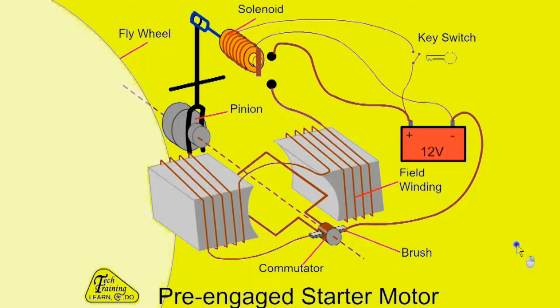The starter motor is used to crank the engine when the key is turned. It consists of a stationary part called the field windings and the rotating motor. When current is fed through the coils, the electromagnets create a magnetic field. This current also passes through brushes and the commutator to the rotor, creating a separate magnetic field. Here we see the magnetic field from north to south due to the stationary winding. The current through the rotating winding sets up a separate magnetic field. The interaction of the 2 magnetic fields causes the rotor to turn.